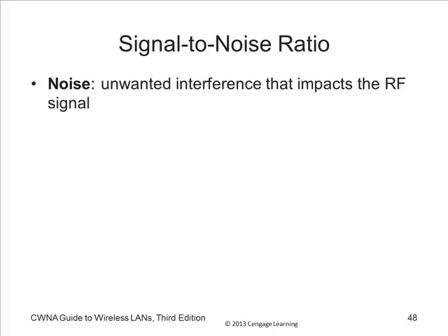What signal to noise means is how weak can the signal be before the receiver can determine what signal was noise. And Trevor talking about the self-canceling, noise-canceling headphones, what they do is figure out, calculate, find, hear the noise, the ambient noise, and now that we've seen that little demo, they just create a signal that's 180 degrees out of phase, and it's canceled. Yeah, noise floor is what this is called.